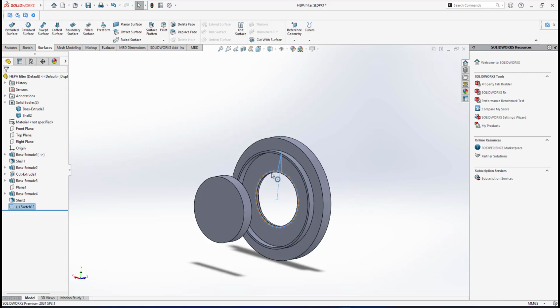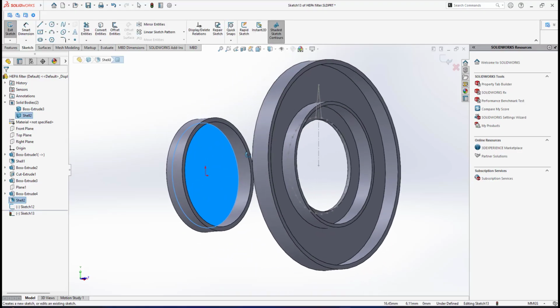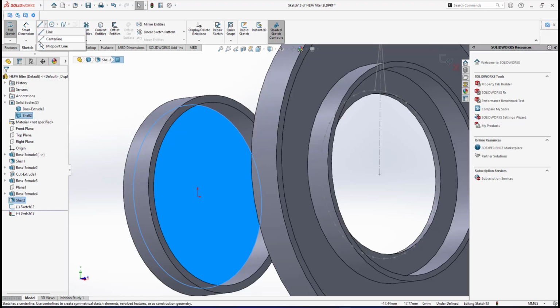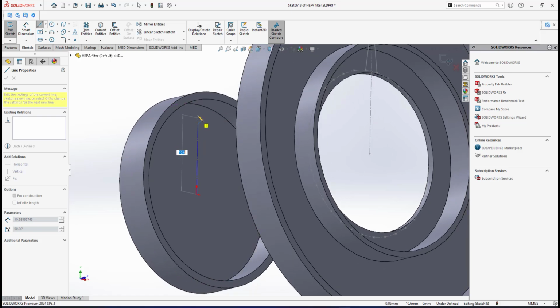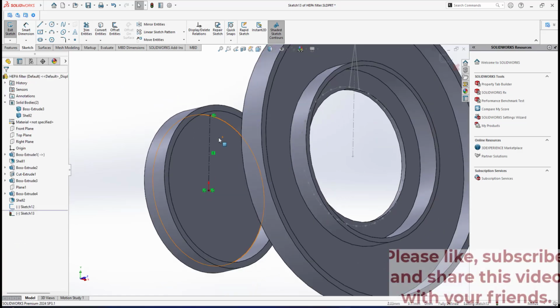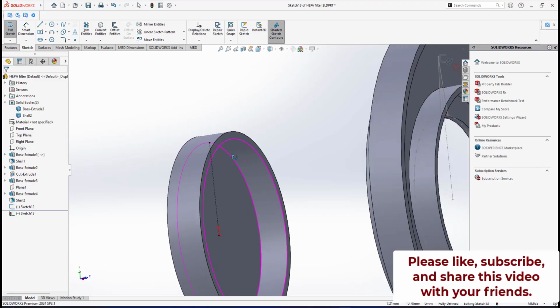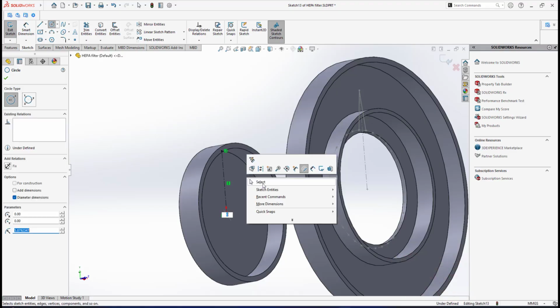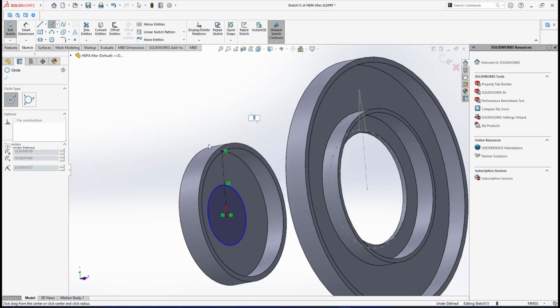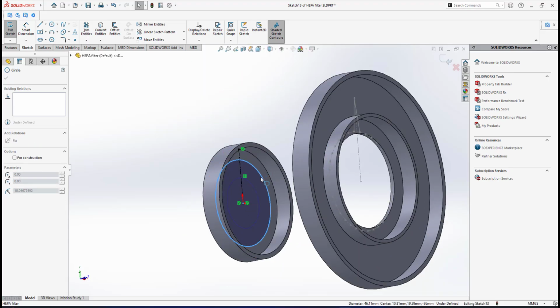So I've done the sketch at the back here, and I will create another at this sketch plane. I will use a similar approach: a center line from this point, making sure it goes vertical and touches that quadrant point. If I do a loft, it intersects with the ceiling of this cap. So I make a circle a little bit smaller. Let me delete this thing. This circle I need to drag to about this size.